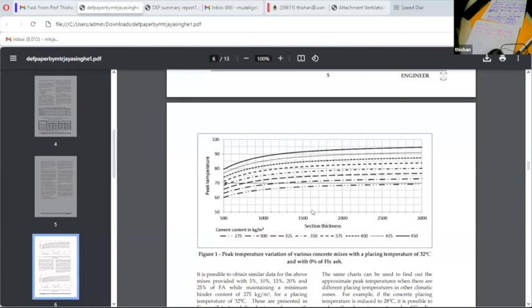But if you reduce the placing temperature by adding water to the aggregate heap the previous day, and then using 40% flaky ice, what can you do? You can easily reduce the placing temperature to about 26 degrees. But let's say you don't have this knowledge. Just allow the concrete to go on. What will happen? There's a risk of getting DEF. Is that clear, Vashita? Yes, sir, clear.